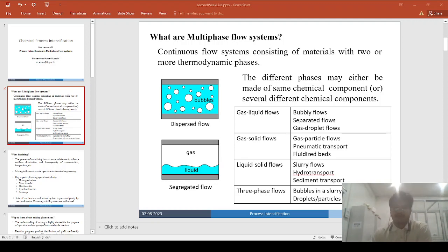Now in the case of a microreactor, the small particles provide a high surface area for improved gas liquid mixing, but they also represent a challenge in terms of pressure drop and fluid distribution among the parallel channels. So these small particles will result in a very high pressure drop.